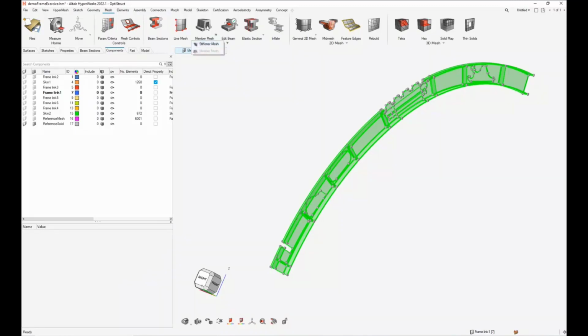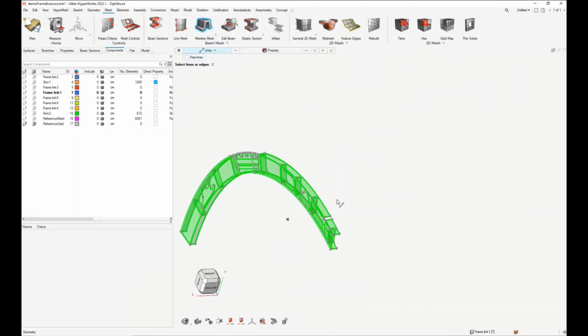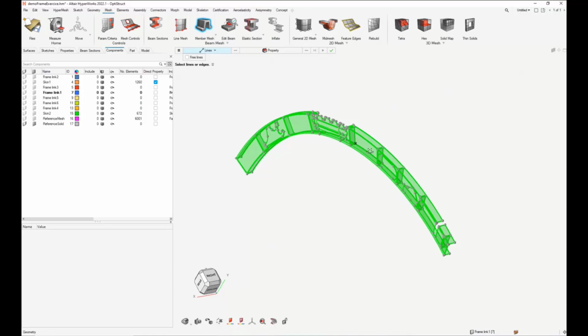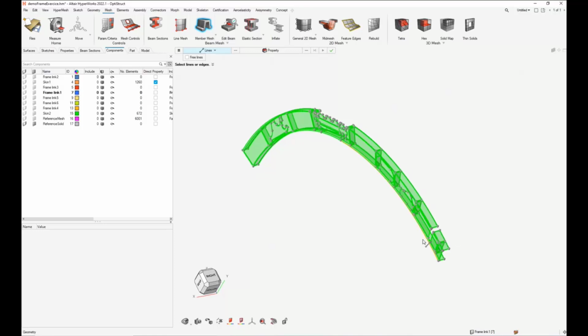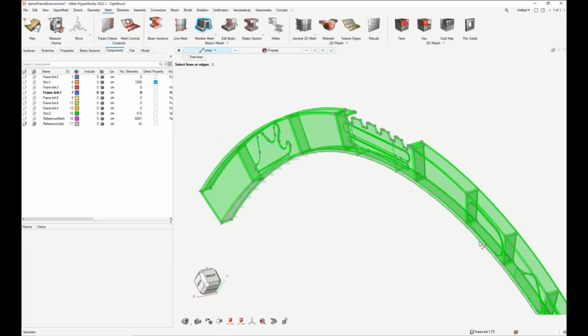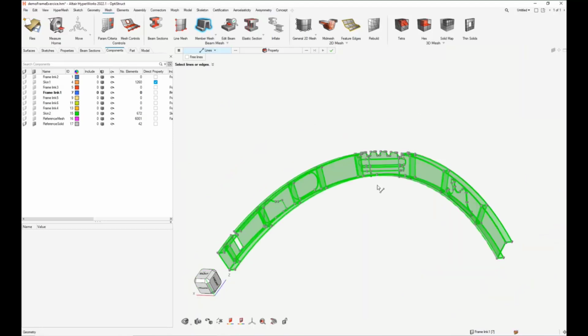If I go not in Stiffener mesh, but in member mesh, just to seed some elements here. And I can even take an orphan line. I just need that tool, yet it's not generating the 1D. So you just need to select where and how many 1D elements you want to represent something. So here, I will generate an element size of 100. And I don't want an auto orientation, but use my own orientation here, and take my orientation vector along that direction. Sure, yeah. Mesh it. So I have 1D without any property assigned here.